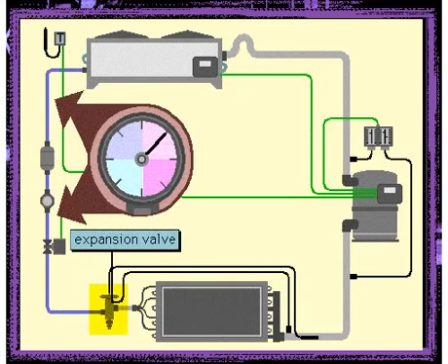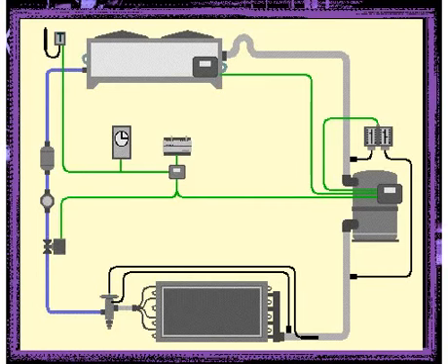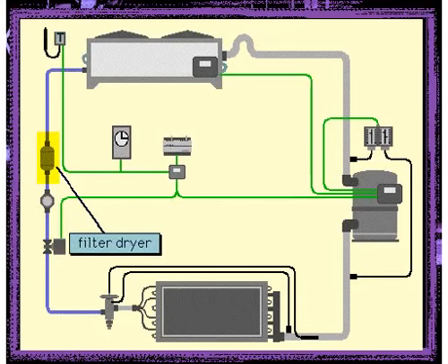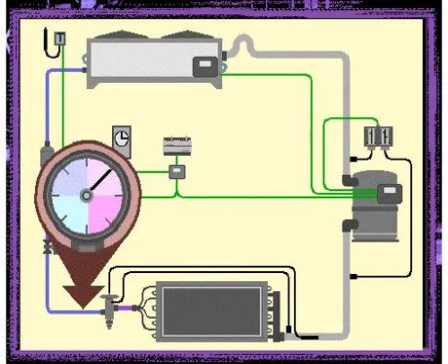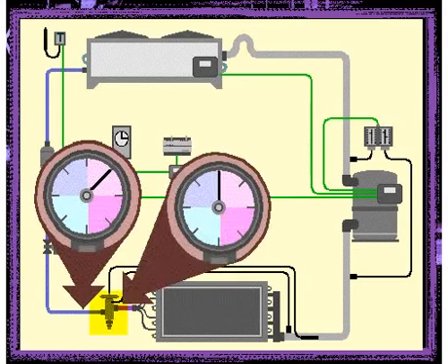At this point, it is at high pressure, with the pressure being close to the pressure it had in the condenser. You can see the refrigerant flowing through the sight glass. As it flows, the refrigerant is filtered to remove possible residues or metal particles. The moisture it may have absorbed during maintenance is also removed by the same filter dryer. The liquid refrigerant at high pressure thus arrives at the expansion valve, which is set to lower the pressure to obtain the temperature required in the evaporator.